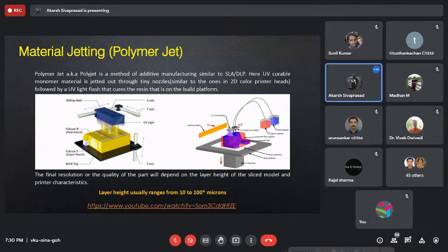They designed this material so that it's photocurable, and at the same time soluble in a solvent or water. Once you're done printing, you can dip it into a bath and all those supports just wash away, leaving no trace, as if it was printed without support. That's a really good method that lets you do more with supports.